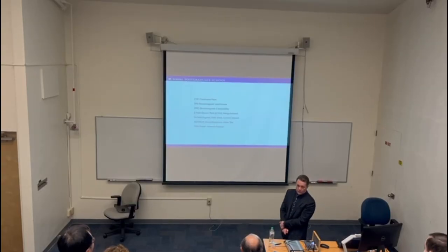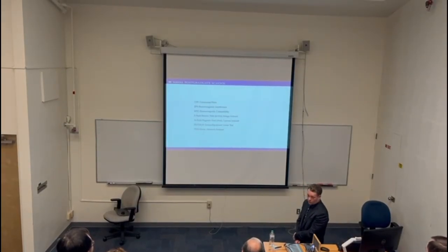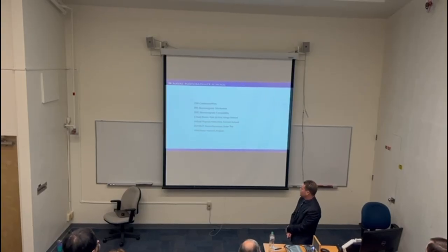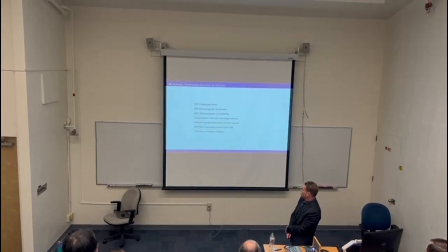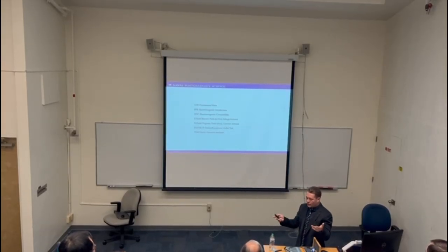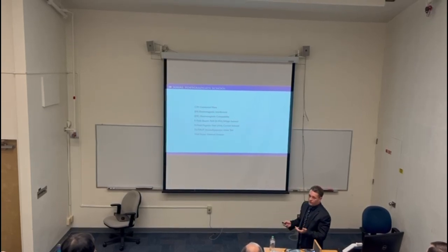We talk about E field and H field. The H field is in particular what we're going to really be looking at, the magnetic field, which is current induced. There's also the voltage induced, which is the E field. And everything that I'm testing, as we'll refer to as the victim, or trying to see if it's immune or susceptible to what I test, is called a device under test.